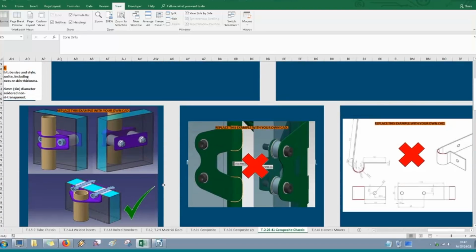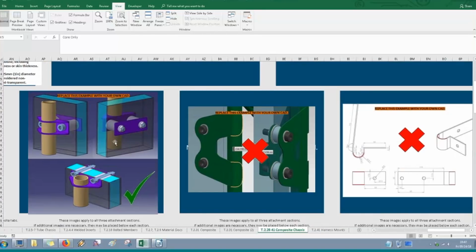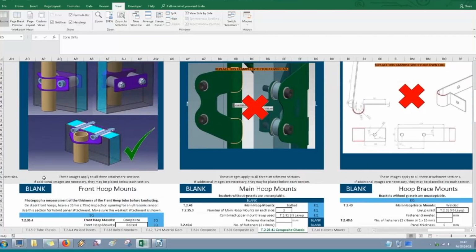The tests are the same in terms of backing plates, inserts inside, tear out and pull out. One thing we get into a lot of discussions of is free edge or tear out, and that's where these two fasteners would tear all the way to the bottom, straight lines, until they popped out the bottom of this composite.